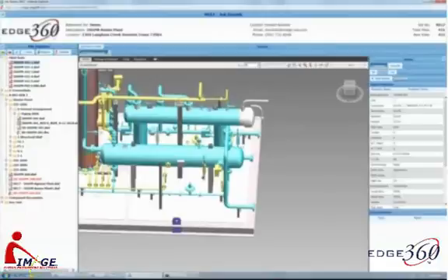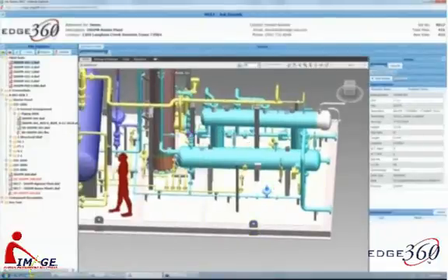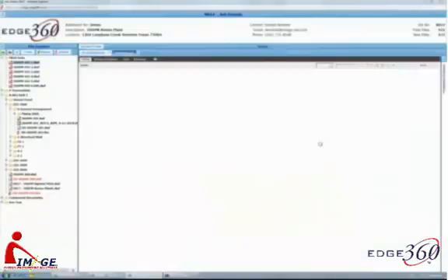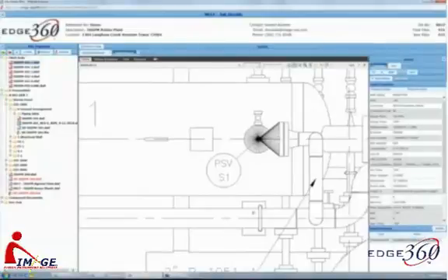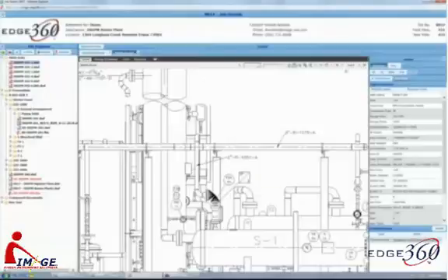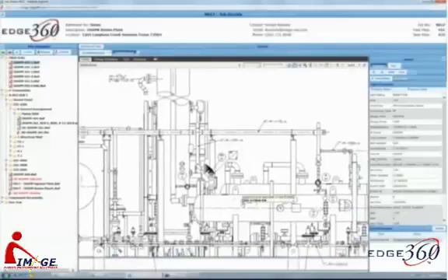Now, if we go and click on this control valve or this PSV valve or whatever, I also can click my 2D button, and now it goes and opens up the GA 2D drawing of that particular piece of equipment, and you can see that it zoomed to the call-out for PSV S1. If there were multiple call-outs, which I think there is, I can hit Next, and you see it took me to sheet 4 where I have another call-out instance for that item.